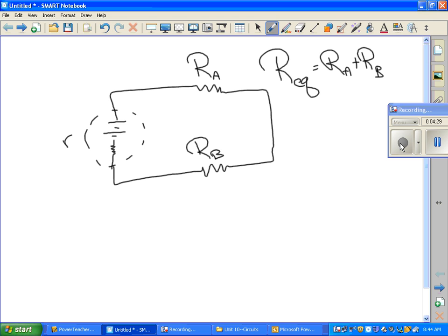So what happens, since the voltage that any of these resistors uses is equal to current times its resistance, I can find the voltage used here, I can find the voltage used here, I can also find the voltage used internally before it ever gets out to the terminals of the battery. That's why a 9-volt battery or a 10-volt or 12-volt battery rarely actually registers that many volts, because some amount of voltage is used internally. Doesn't a wire produce this? The wire does too, but it's pretty negligible if it's a good wire.